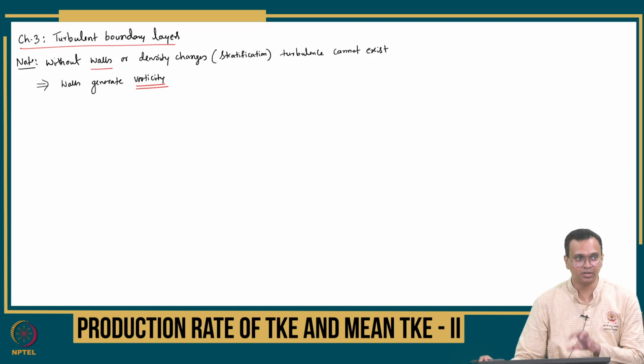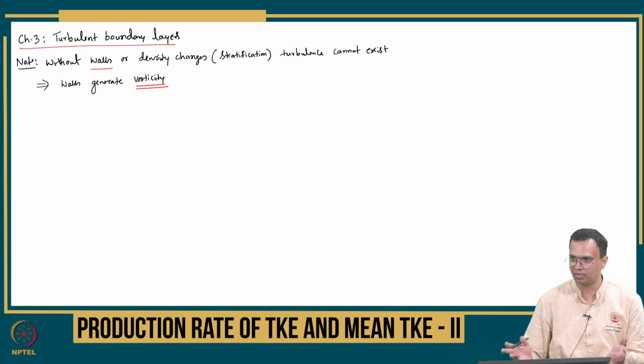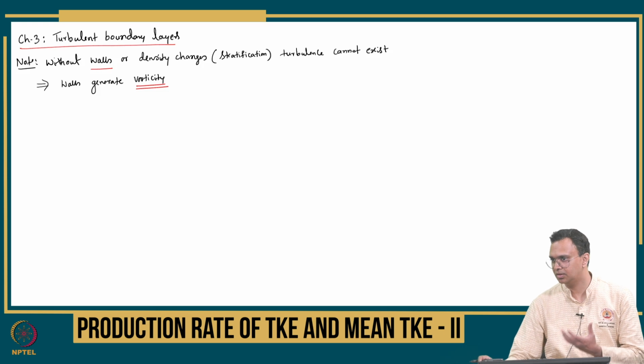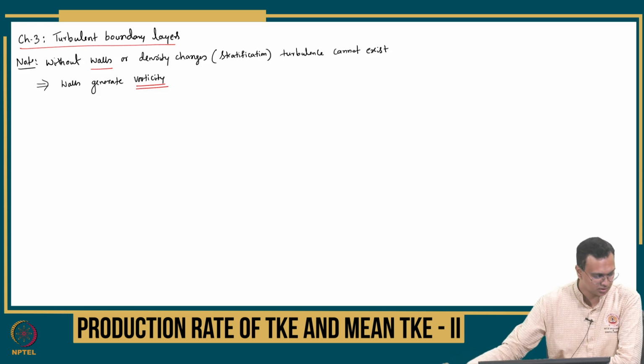3D vorticity fluctuation. The presence of three-dimensional vorticity fluctuation is important. All you have to do is, if the three velocity components are given to you in three-dimensional space and time, you compute whether three-dimensional vorticity fluctuation exists. If it is non-zero, yes, it's a turbulent flow field. Okay, so vorticity is very important in the context of a turbulent flow.